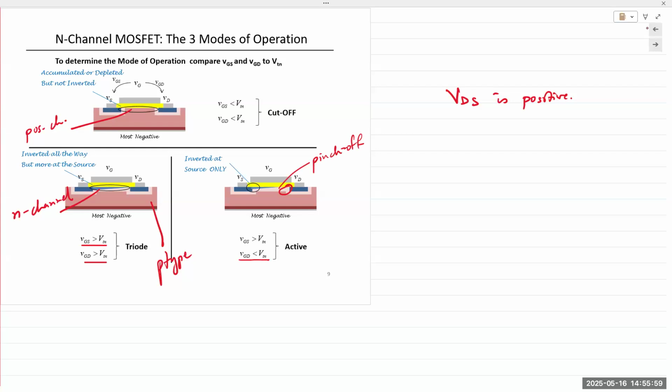It pinches off, but there's a small gap that's left behind, and all of the electrons still have a pathway to flow through. So it's pushed through that small gap. Even though the channel is closed, physically, there is still a small gap. And there's a very high charge density because the same number of electrons keep flowing through there.